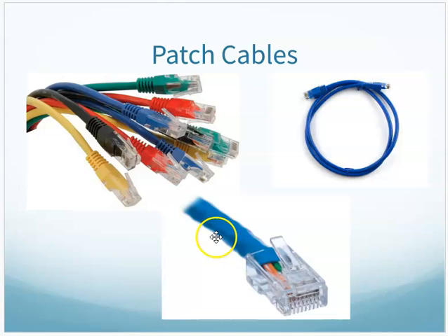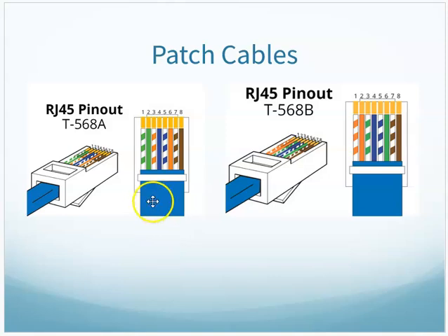And my patch cables have this type of connector on the end, a modular 8-pin connector. A lot of us call it RJ45. That's kind of a slang name, if you will. That's a modular 8-pin connector. And they do have pinouts, the 568A and 568B color code pinout for terminating that patch cable.